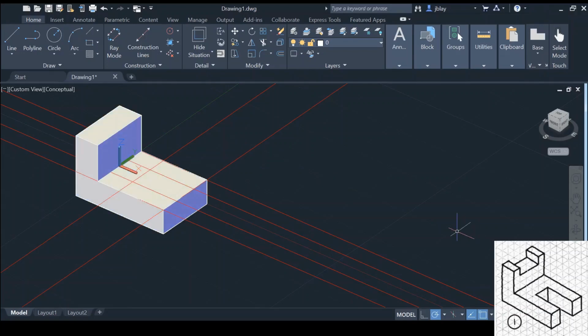So if we try to press pull that area, let's see what happens. Does it let us select it? No, because there are construction lines. That won't work. We actually need to draw object lines in that space. So let's do it. Let's use polyline. I actually don't need to use polyline or join for press pull. Usually, sometimes it works a little bit differently.